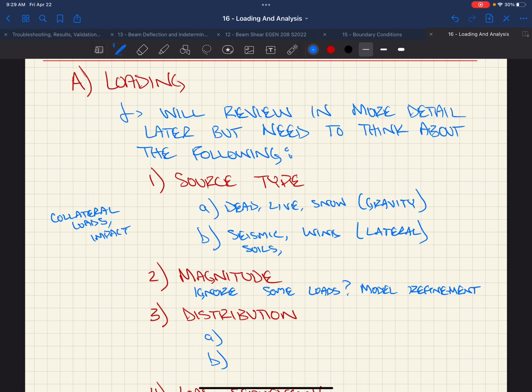So if you grabbed the worst case, but because of this behavior, if you did a linear interaction, and this is a non-linear interaction diagram, if you did a linear interaction diagram, which is conservative, then you could do that. You could just say maximum, maximum, plot it. If it was inside this, you'd be okay. But because you have this weird thing going on, that axial load might kick you up above the curve. This MU, PU is right here. But if you use the actual moment demand at that axial load, you might be down here and it might not be okay.